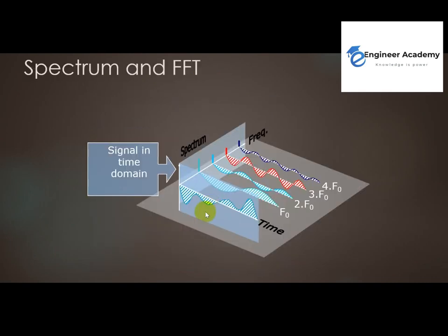But in this case, if we talk about the time waveform, how can we detect exactly what the source of this time waveform is, especially if we have many parts in the machine? Like in this example, we have four parts in the machine. For example, the motor has a rotor, two bearings, not one bearing, the rotor itself, the stator, many things, and then it's coupled with the machine using a coupling, and the pump has a bearing, has an impeller, many things.